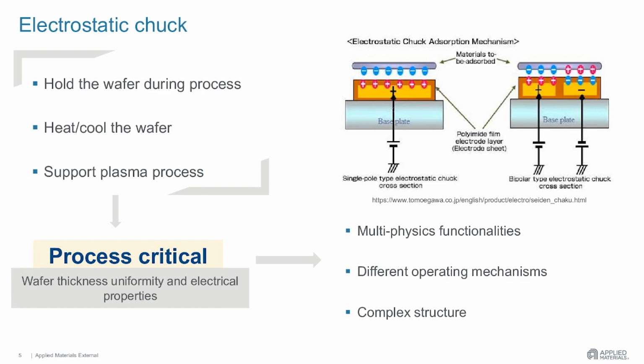To provide a few more details on what electrostatic chucks are, their primary purpose, as I just mentioned, is to hold the wafer during the process. They have to be planar. There shouldn't be any sliding because eventually these affect the wafer thickness uniformity.